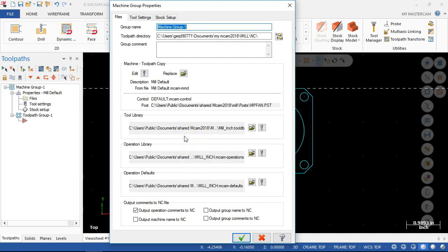So if you have the side mount tool changers where tools pretty much go in and they come out every 2 to 3 months, just for inspection and cleaning or as tools break or wear. So in that case, we could have a tool crib, and position 1 is always my 1/2 inch end mill, and position 2 always my 3/8 inch end mill, and down to 1/8 of an inch. If we're doing large stuff, it may start at 3/4, and then we jump by 1/4 inch increments to cover the widest range of machine operations.